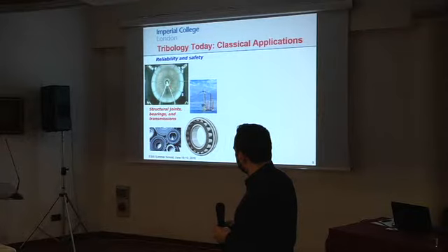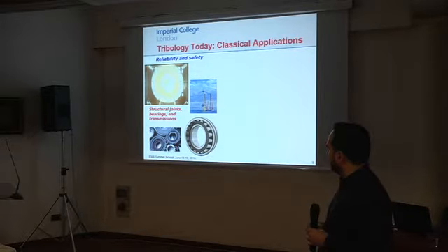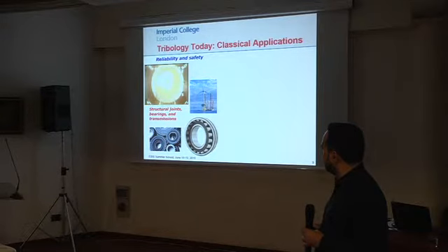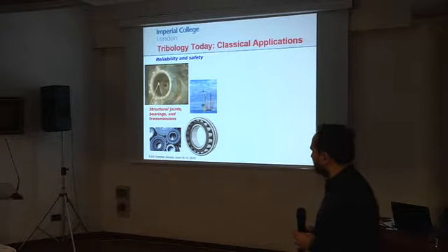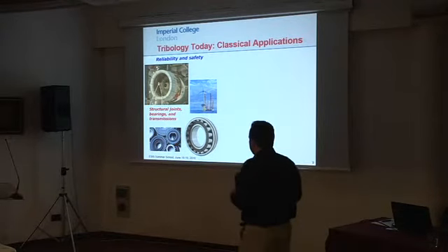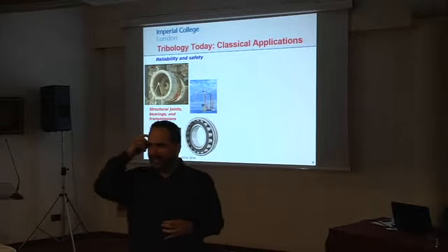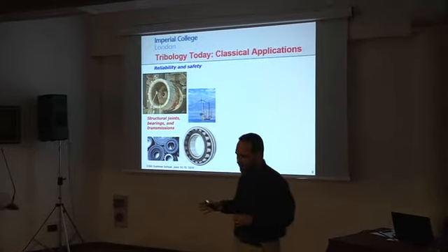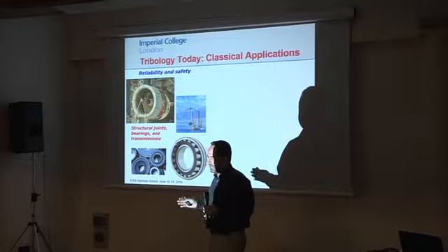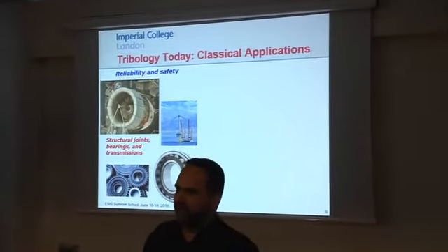That is a blade coming off a disc in a Rolls-Royce engine. That's what happens at low speed. That's what happens at high speed. Right, so this is a successful test. You look at this and you think, successful? Not really. It is indeed a successful test. So this is a test that any engine company needs to run to make sure you can certify to fly.